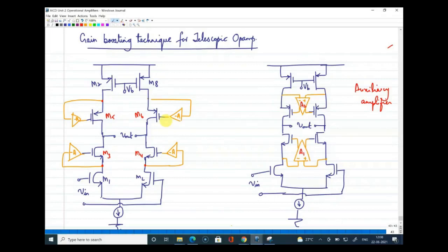Instead of getting the output of this and then again designing another circuit, and then looking at the swing and other constraints of that second amplifier again, that becomes a regular two-stage op amp when you have that kind of structure as the first stage and you directly add a CS amplifier. Here you have only one stage. Within that stage, you are including this technique.